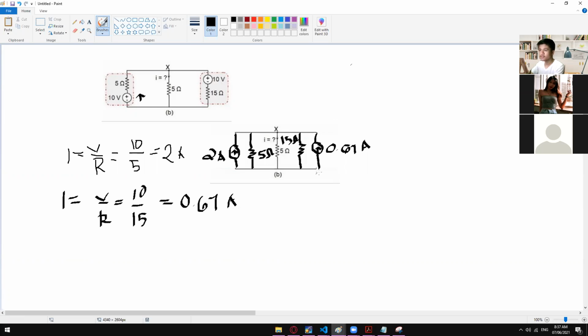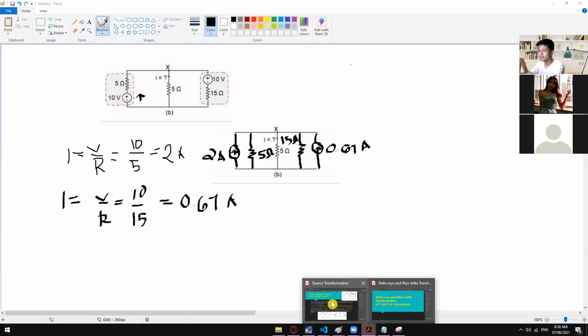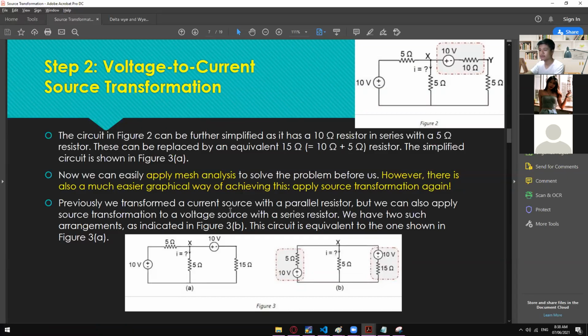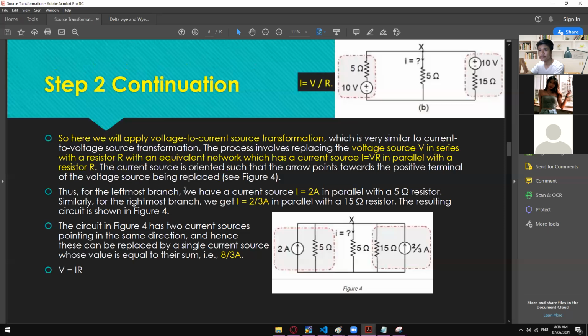All right. In here, we have another thing that we can do to simplify this further. We have a parallel connection of current sources, and they have the same polarity. So we can actually add those two currents into one current, arriving into three resistances. We can combine those three resistances into a single resistance. But before that, let's see what the next thing is that we'll do on step number two.